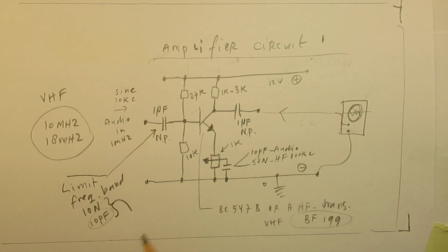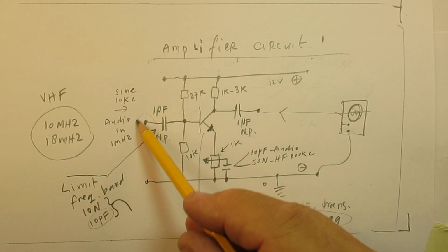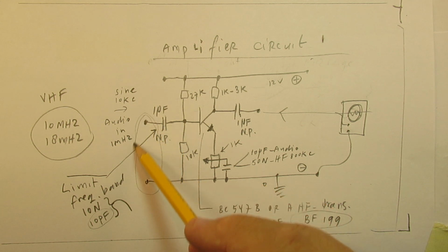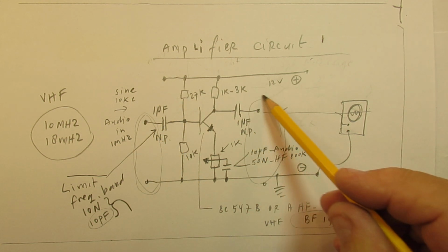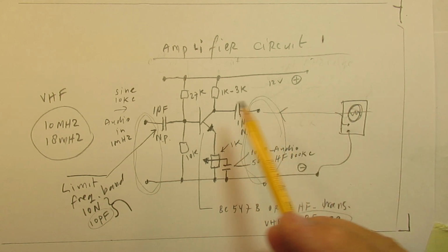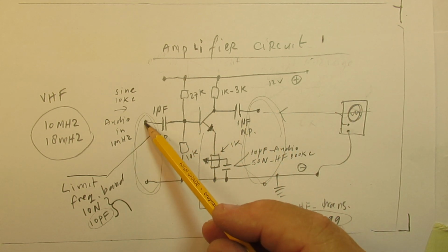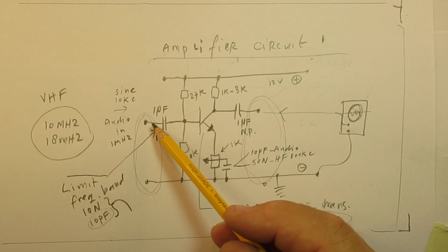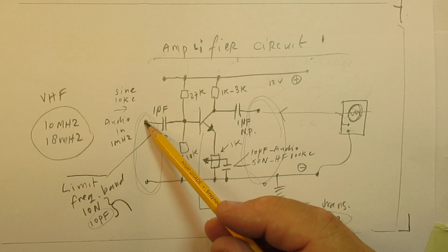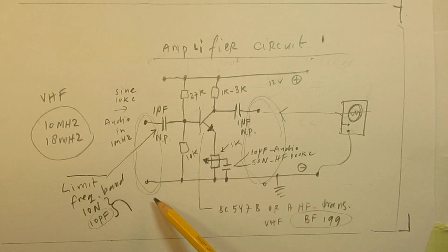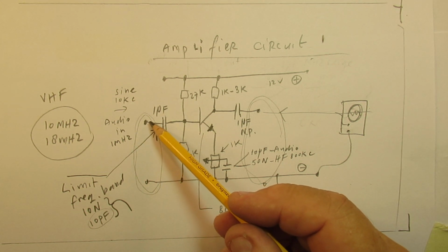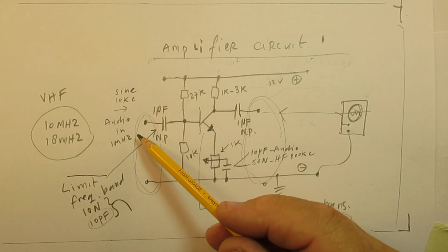Of course, I did not talk about what's present here at the input of the amplifier and what's present here at the output of the amplifier. When we see that bare lead here and let it hang into the air, there is, say, a resistance between that bare lead and ground in the order of 30 mega ohms or so.